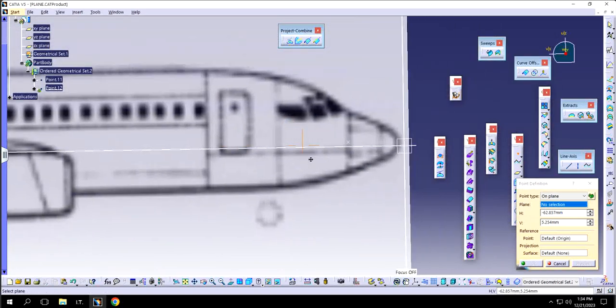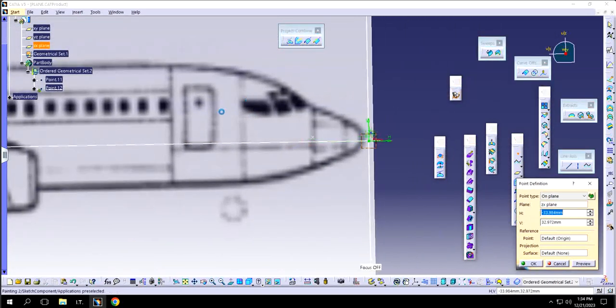So I took one point there. I can see that I might need one point here as well, somewhere in the middle of it, somewhere here. I'm using points because it's easy to control points versus using a spline. You could have made the guiding curve directly with a projection sketch, just make a sketch that will consist of a spline or even a 3D curve.